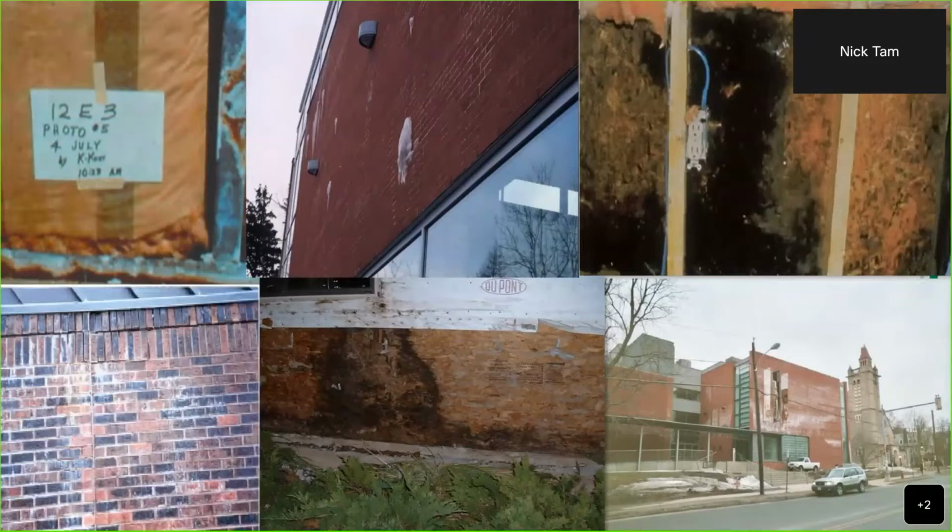You also have to think about the facade and the exterior side. The middle picture, bottom left and bottom right are really good examples in cooler climates where moisture is becoming an issue and causing deterioration of the brick facade. And this can all be due to improper detailing and not taking into account how continuous this membrane should be across the board.